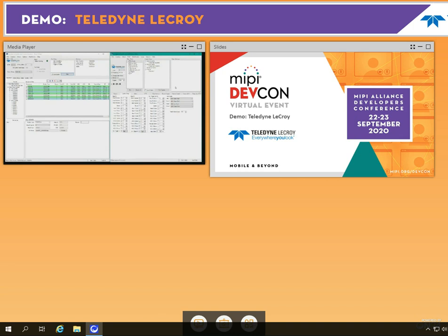The user can use up to 4 different user-defined decodes to also start, stop, or trigger an external piece of equipment. For this demo, we will look for the first frame start and capture until we see 11 frame ends. This should allow us to capture 11 full frames of traffic. Once we start capturing, the Envision looks for the first frame start and captures and fills its 4 gigabytes of memory until it sees the proper number of frame ends.